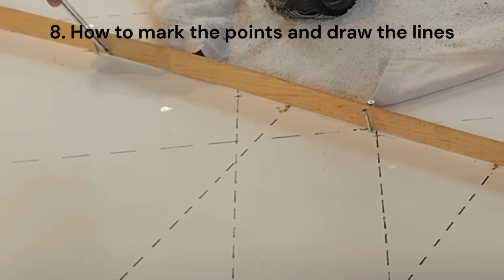Now it is time to draw the curved station lines with the same pen color as the points. For this, take a batten, relatively soft wood, or use a worn-out bandsaw blade cut as one long piece. Fit the batten with screws or nails on both sides at each point you have marked. Draw a line from start to the shear point. If deck curvature, draw this line in a similar way.